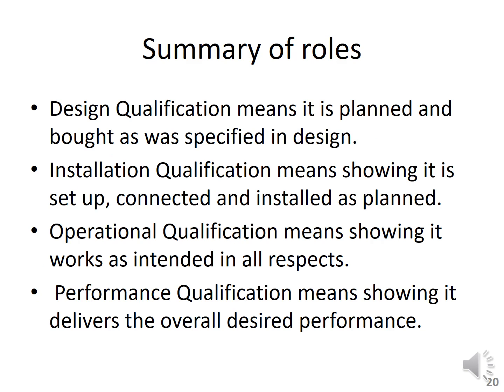A summary of the roles which are performed by all four phases. DQ, design qualification, means it is planned and bought as it was specified in the design. IQ, installation qualification, means showing it is set up, connected and installed as planned.